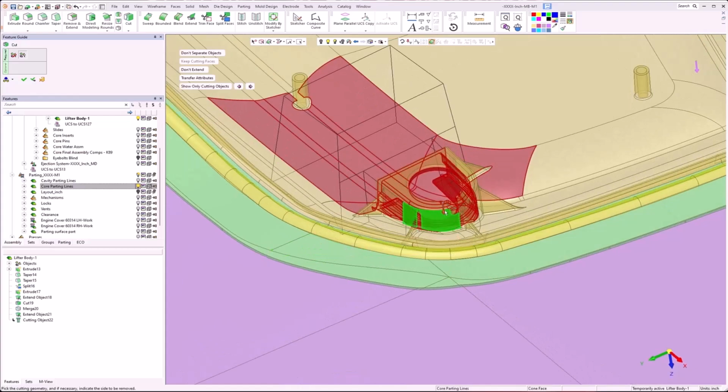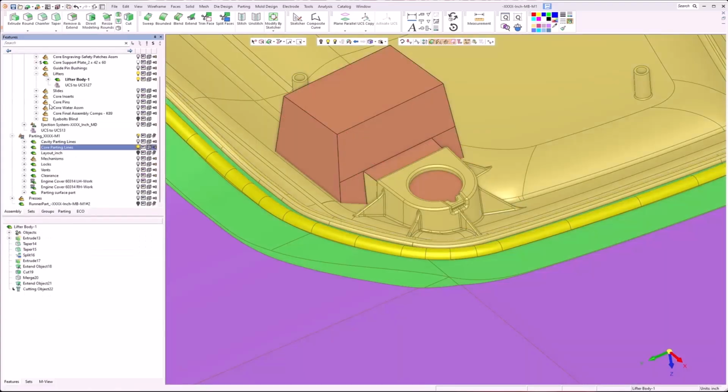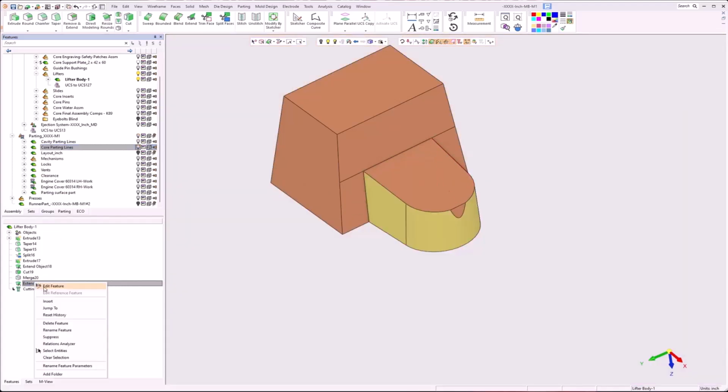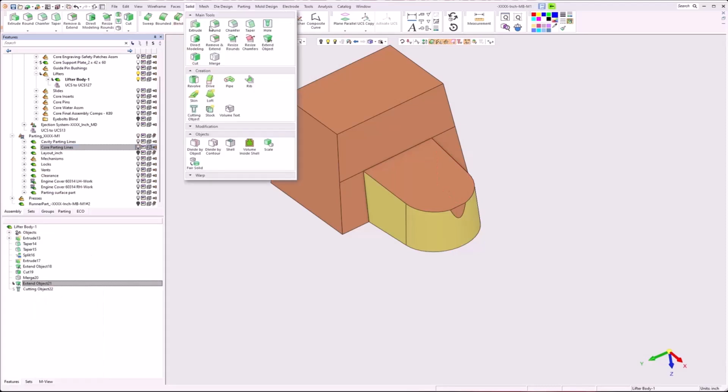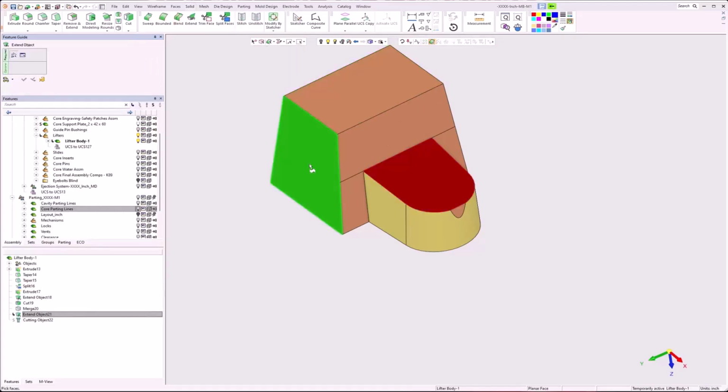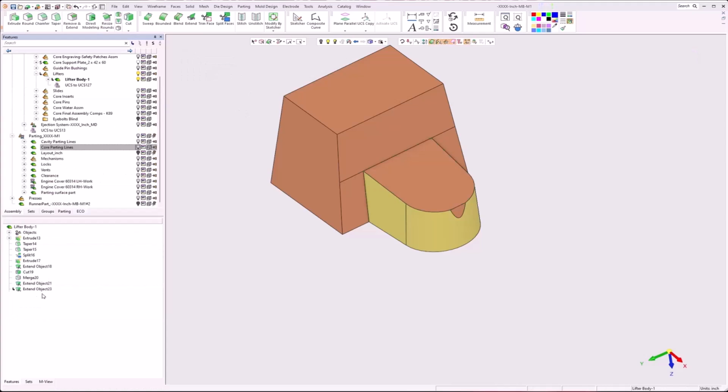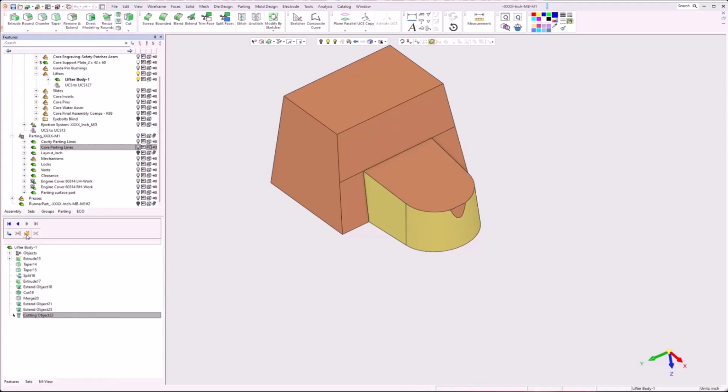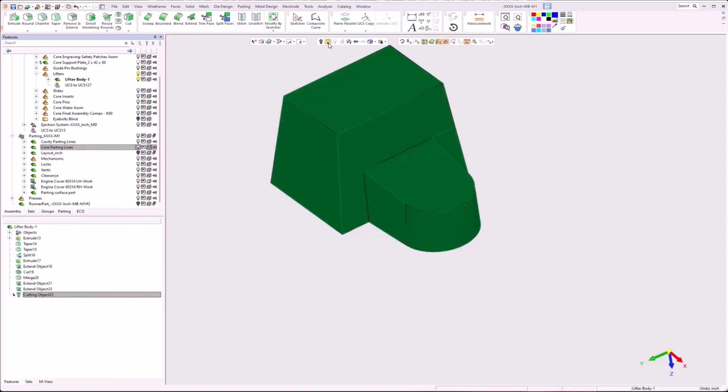And it's failing, and don't give up too easy here because the issue has to do with this face for face. Remember, I replaced face and put it on there? I am going to insert above my cut object, extend object, pick this face, and I'm going to offset it 1/10 of a thou of an inch. I can then jump to show you the cutting object has updated.